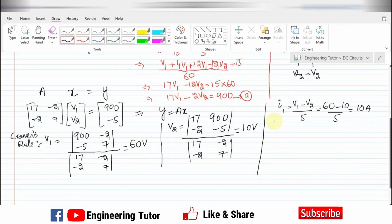So the power supplied by the 15 ampere source is equal to I times V1. So I is 15 multiplied by V1, which was 60. So this was equal to 900 watts. Yes, it was 900.